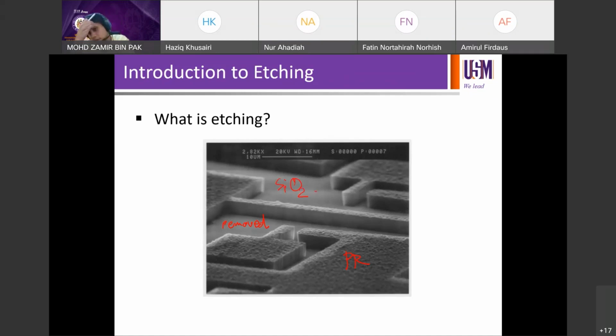If the resist is coated on some other material, then that material will be something else. We assume it's silicon dioxide. Because say you have grown a very thin layer of oxide, and then you have done lithography, and then you develop, and there will be open areas and remaining areas of the resist, and those open areas should be silicon dioxide exposed to the environment.